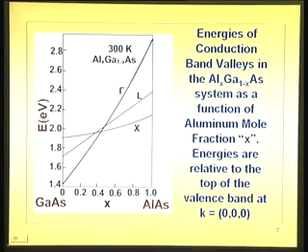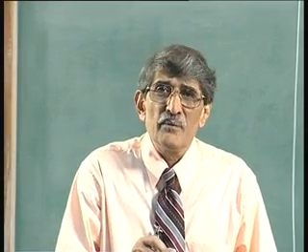In fact, if you see indium gallium arsenide, as x is varied, it will not be really straight. So, the band gaps that you really get are slightly different. Where x equals 0.47 gallium concentration, you get 0.75 electron volts band gap because of its nonlinearity. So, now let us go back to x equal to 0.4. Let me remove all this now, because we understand these are the diagrams. These only represent the directions along the crystal.